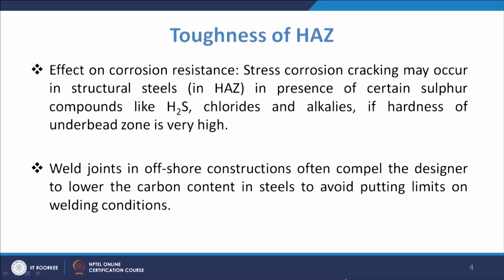So, that also very much takes place in structural steels in the presence of certain sulfur compounds, like H2S or chlorides and alkalis, if the hardness of the underbead zone is very, very high.